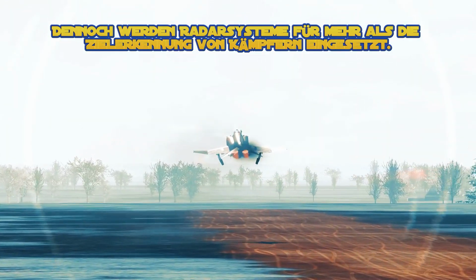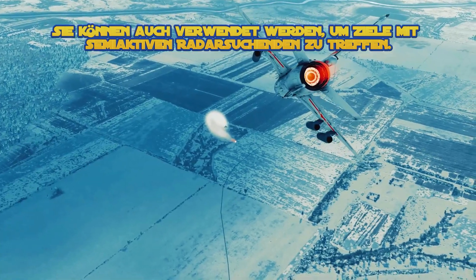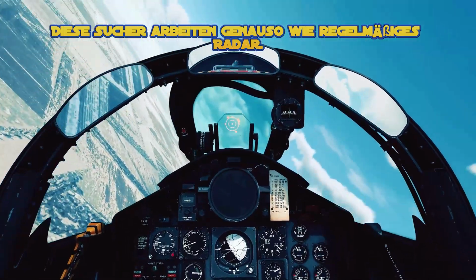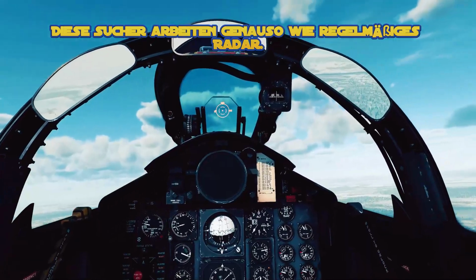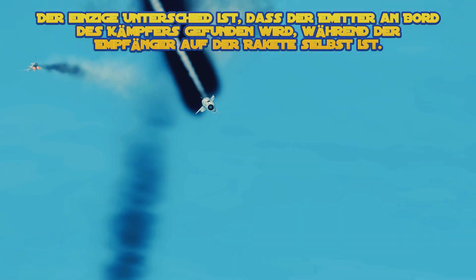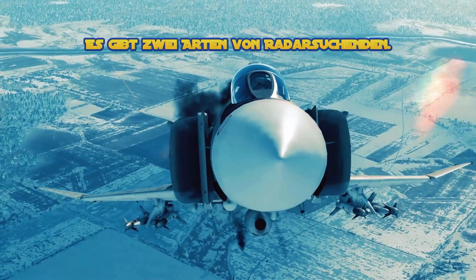Still, radar systems are used for more than target detection on fighters. They can also be employed to hit targets with semi-active radar seekers. These seekers work much the same way as regular radar. The only difference is that the emitter is found on board the fighter, while the receiver is on the missile itself. There are two types of radar seekers.